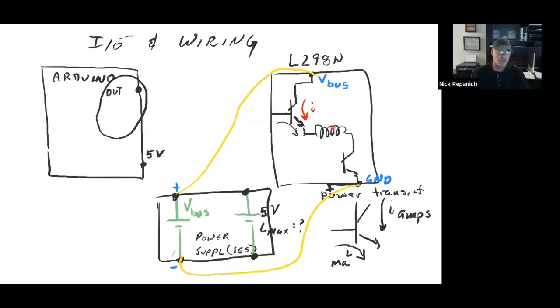I did this one time. I was trying to find something to work on a radio, and I just grabbed a bunch of different 12-volt supplies, and they were all 2 to 3 times the amount of current. Every time I keyed up the radio, it shut off. Finally, I hooked one that was like 5 times the amount of current. I keyed up, no problem. And it's because, oh, duh, Nick, it's an inductive load. So from now on, when you hook up loads, especially you mechatronic engineers, think inductive load versus resistive load.